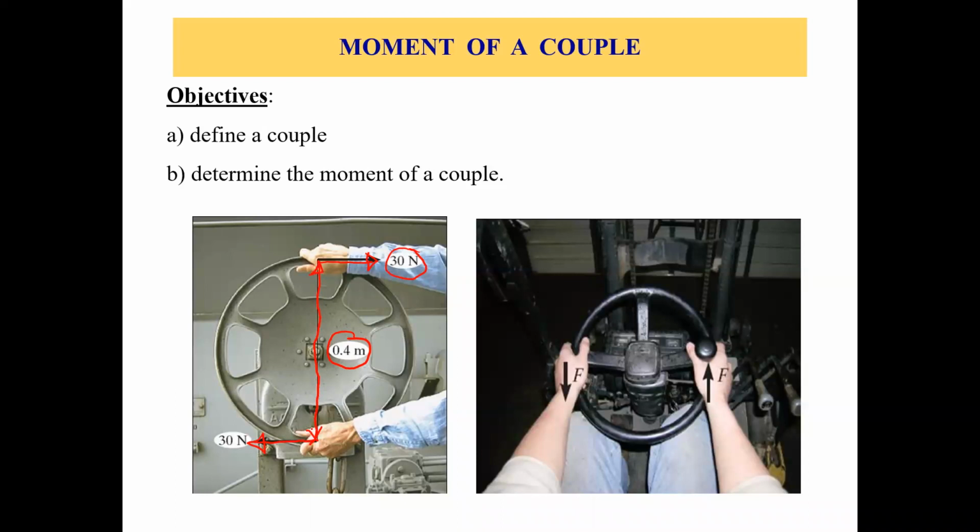So once we have two forces which are equal and opposite and parallel to each other, and they have some distance between their lines of action, then these two forces are called a couple. And the moment created by this couple is called moment of a couple. So we discussed what is a couple and moment of a couple, and we are going to learn the same in this topic.